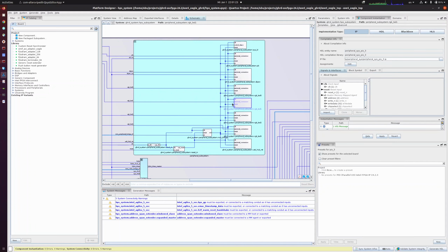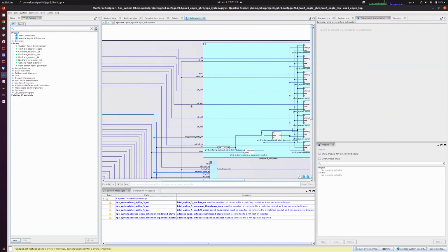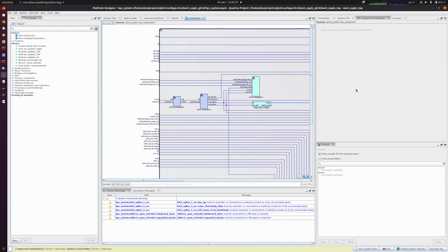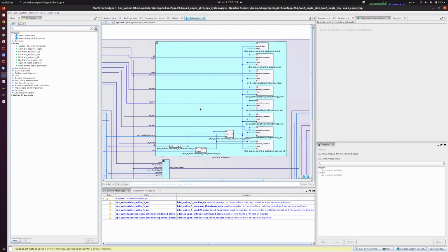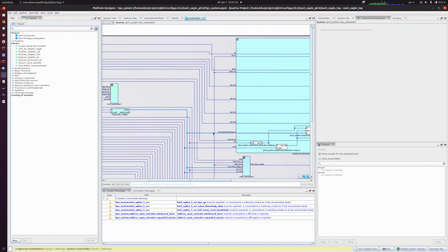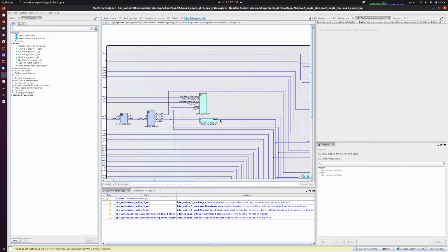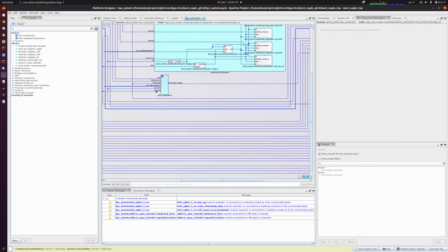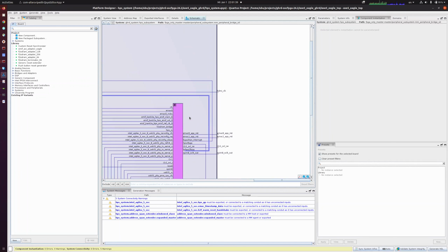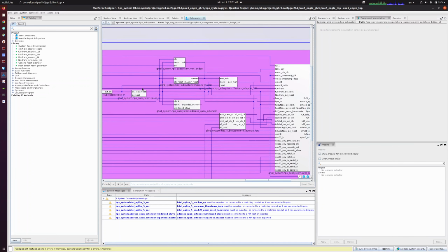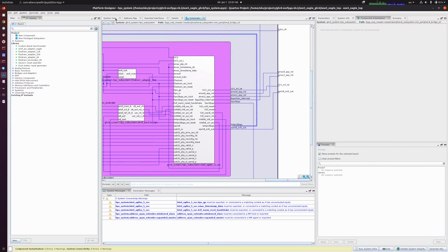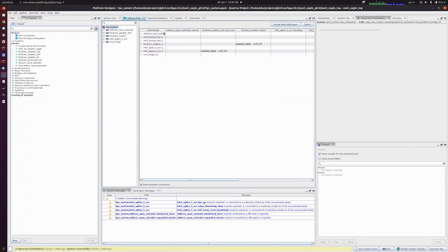We can write into these things, via the lightweight HPS to FPGA bridge. Now we just have to understand the right address.